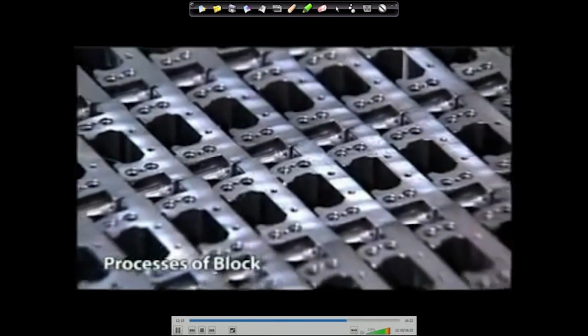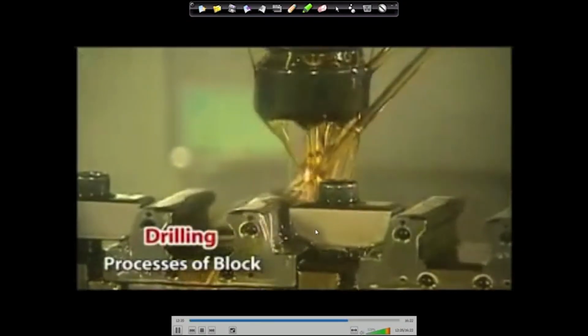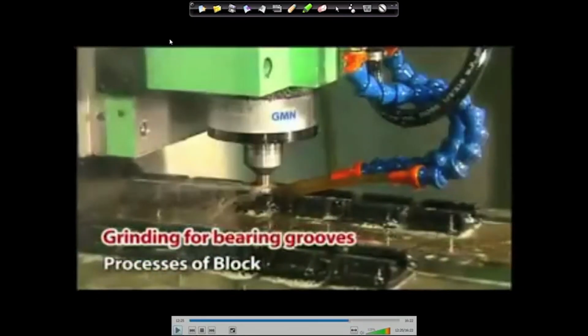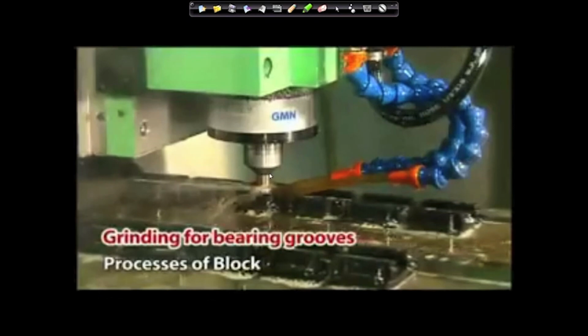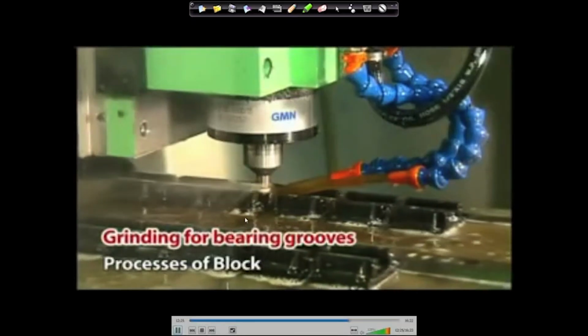And the same thing we have to do for the block also, because we have to mount one block on the top, then again the drilling and all the operations are the same, and again you have to create the reference surface, because both are matching parts. What we discussed earlier was for a single component, but if you have two components which come into contact with each other, then you have to create a reference surface for the other one also. After that operation you have to grind the bearing groove also, because you have to make sure there are no dimensional problems. Tolerances should be as tight as possible, so that you avoid any problem at a later stage.